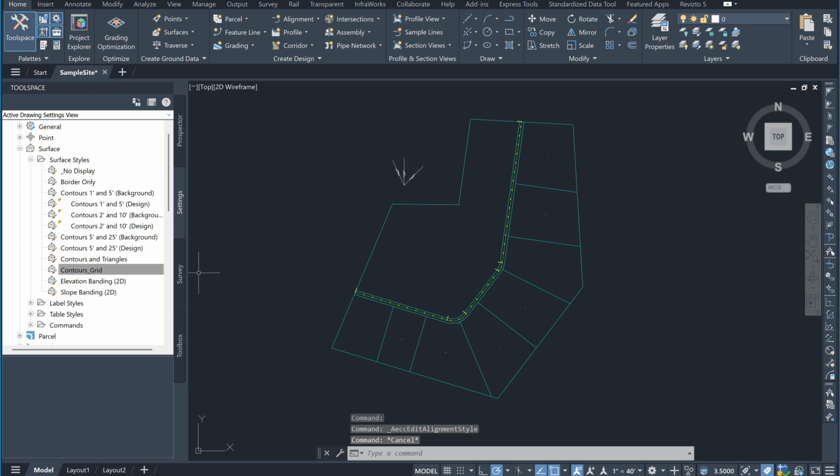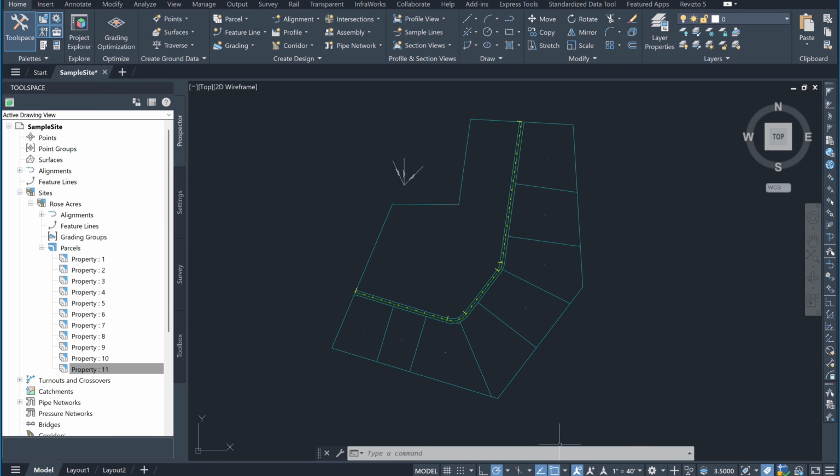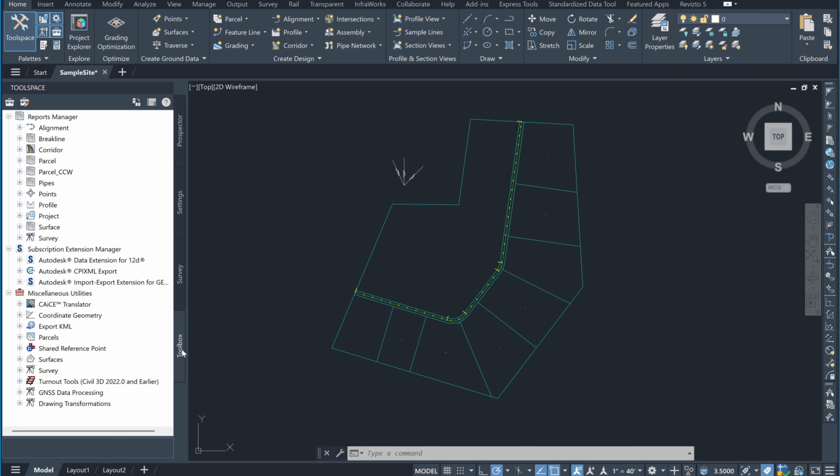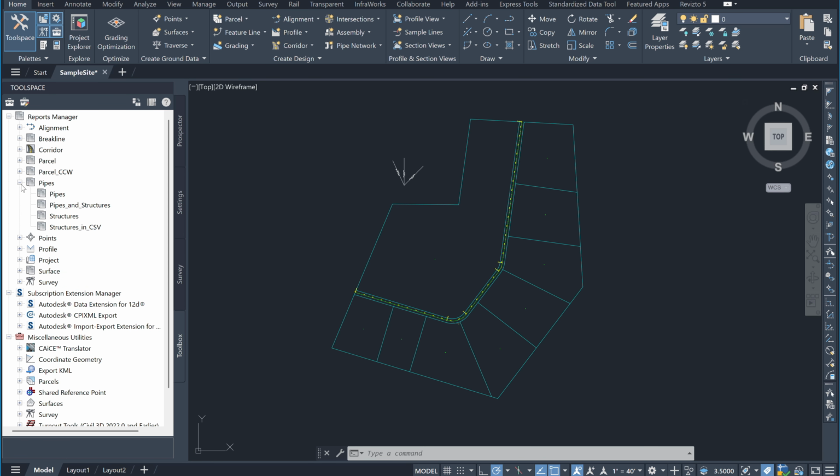In today's tutorial, we covered several important Civil 3D workflows. First, we learned how Prospector allows us to quickly locate objects without manually searching. Next, we changed drawing scale and learned how Civil 3D manages annotation automatically. We customized tooltips to reduce drawing clutter. We created custom label styles. We created surface object styles. And finally, we explored contextual ribbon tabs. These tools may seem simple individually, but together they create a much faster and more organized Civil 3D workflow. The more you understand how Civil 3D manages objects and styles, the more efficient you will become as a designer.